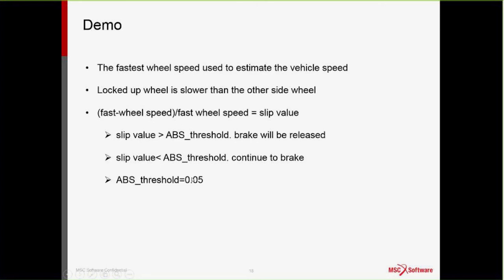When this slip ratio is larger than a threshold, we need to release the brake to maintain the steering of the vehicle.